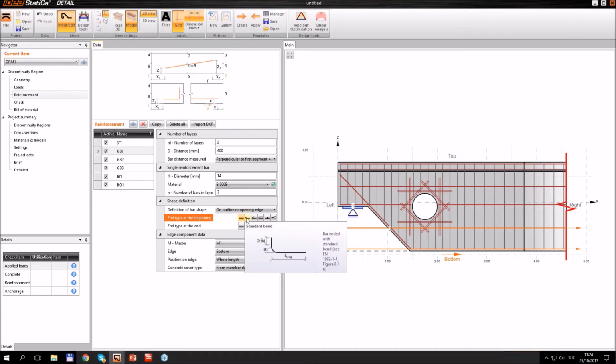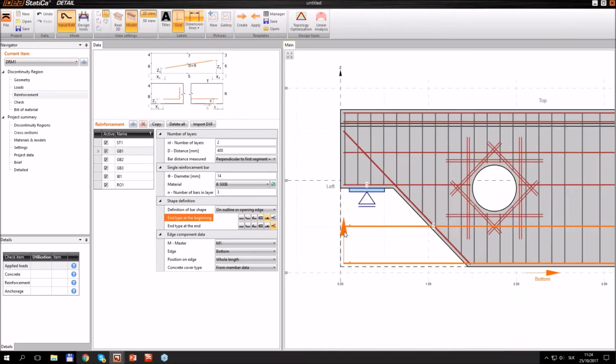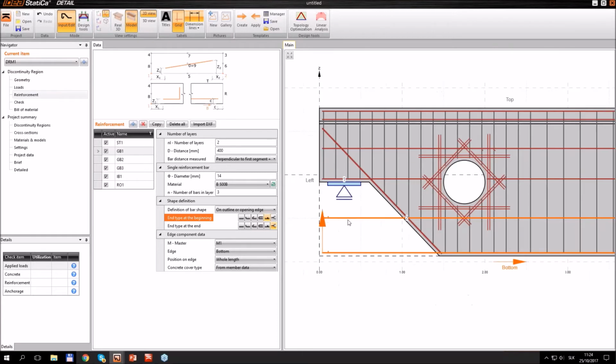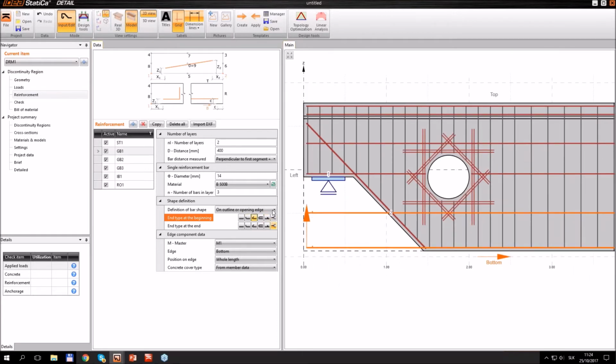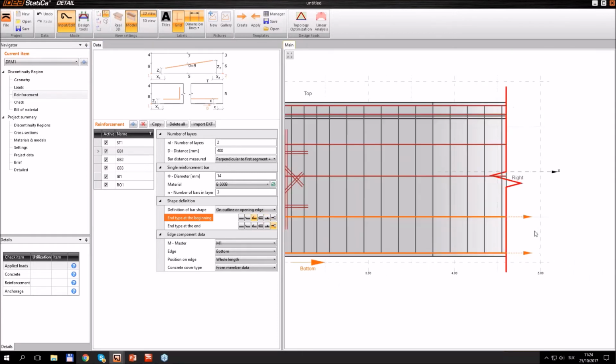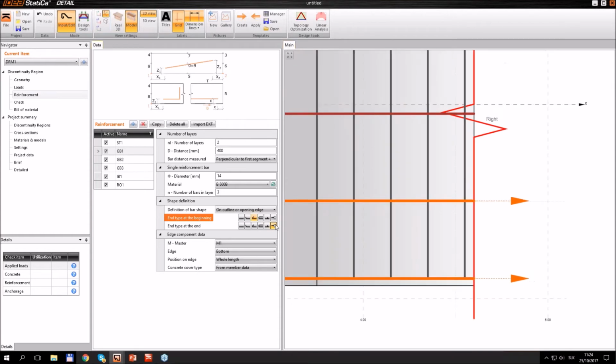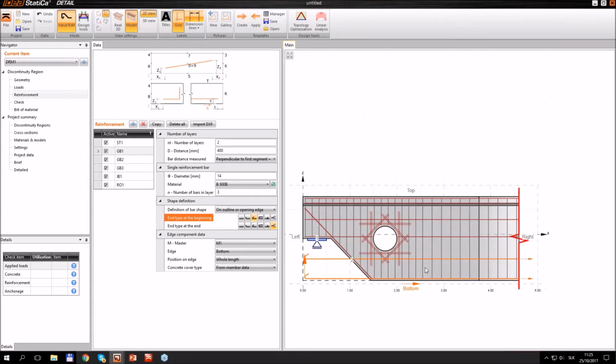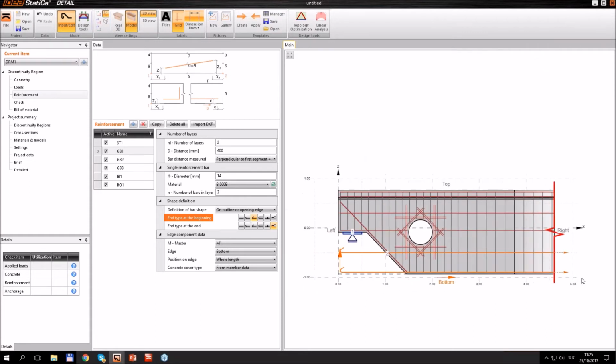So there is basic anchorage, then I can do some bending, hooks, loops. It can also be welded, which has its own mark. Or, as I showed you, it can be a so-called continuous bar, which we assume will be fully anchored at a given value next in the beam, right? So it continues to the rest of the beam.